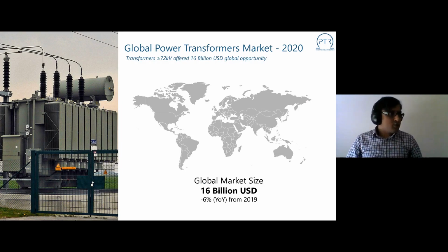It really makes sense to segment the transformers market into power and distribution transformers, as I discussed earlier, because different market trends exist for power and distribution transformers. There are different definitions out there in the market. Some definitions follow MVA, and we are looking at voltage from a system voltage application point of view, where anything higher than 72 kilovolts would be considered power transformers, and anything up to 1 kilovolt is considered medium voltage transformers.